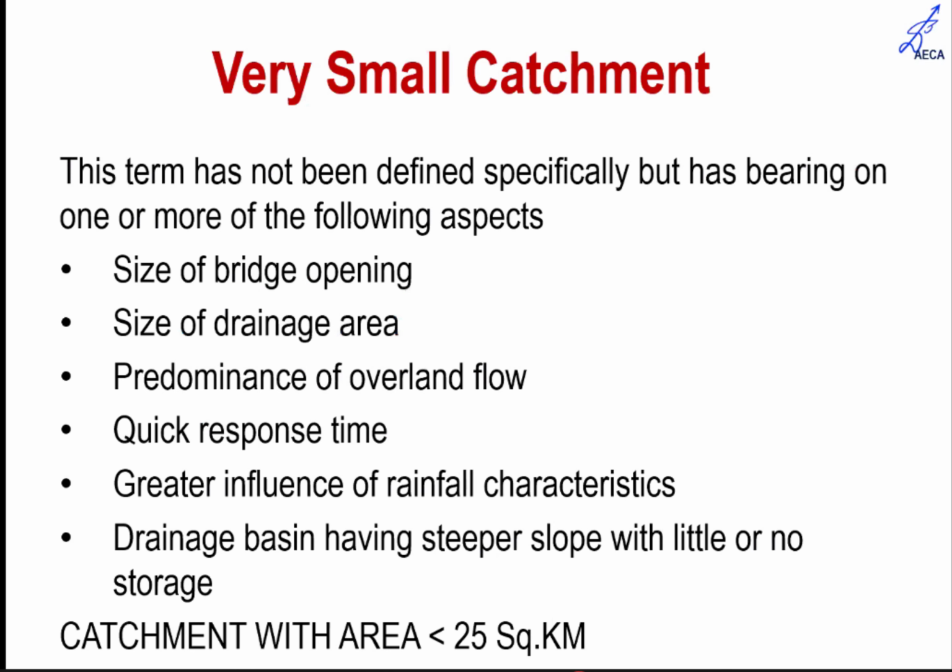So what is a small catchment? Now this term has not been defined specifically, but it has bearing on the size of the bridge opening, the size of the drainage area, the predominance of the surface runoff, the response time of how quickly the channel is filling, and the influence of rainfall characteristics is more on a smaller catchment.